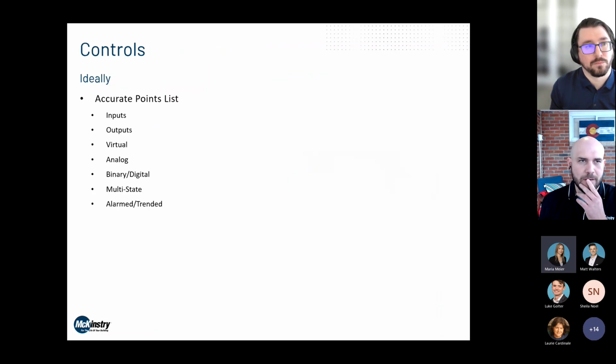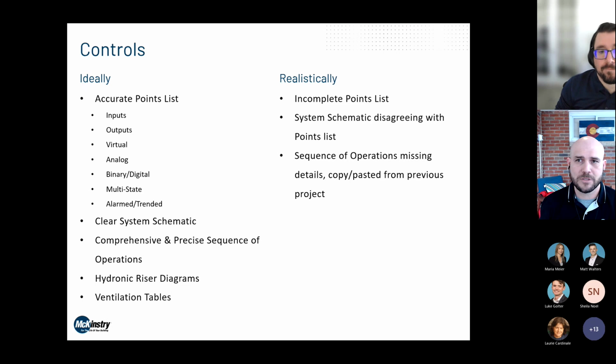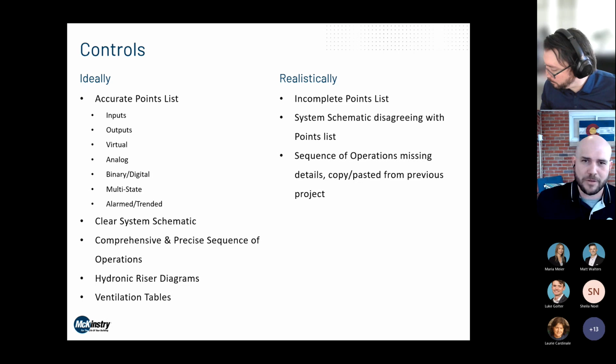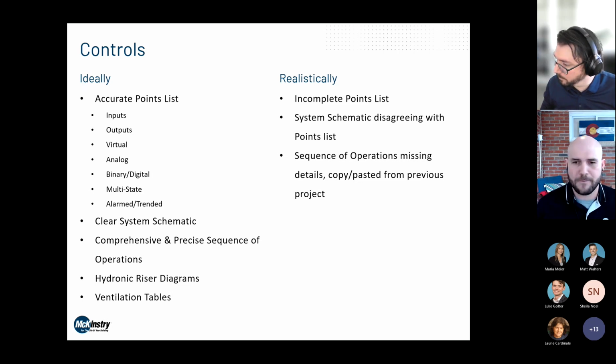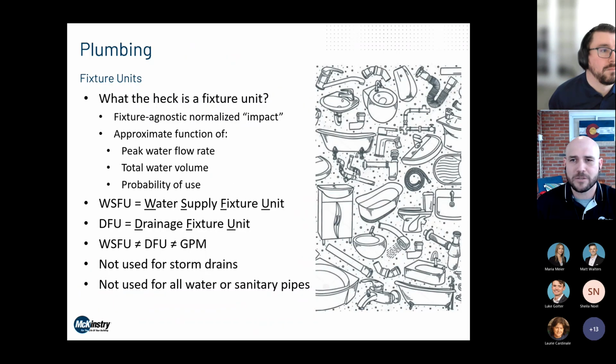Yeah, with regard to that, thanks Maria for bringing that up. We recommended that in large part because system capacities degrade over time, and certainly Hillsborough has been notorious for not keeping up as well as they should have with that. So to make sure that the system can still deliver its initial capacity come the end of its life, that was one of the reasons. And coils get dirty and heat doesn't transfer as well. There were a few things we put in there to help mitigate that.